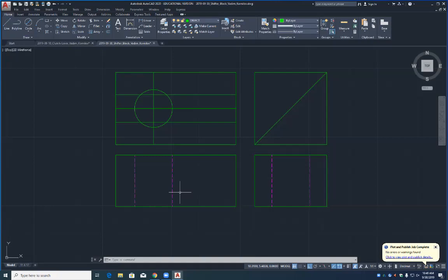Mike, if I say that the 0.5 is an indication of the slot in relationship to the center of the hole, yeah, you could say that. The total width of the slot is 1 inch plus or minus the tolerance, and 0.5 is the relationship to the center plus or minus the tolerance.